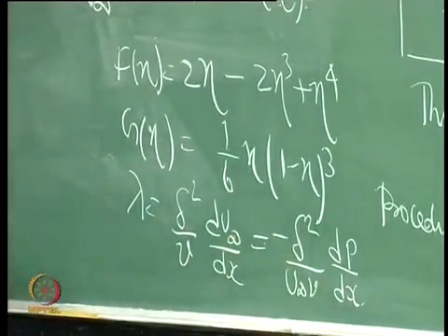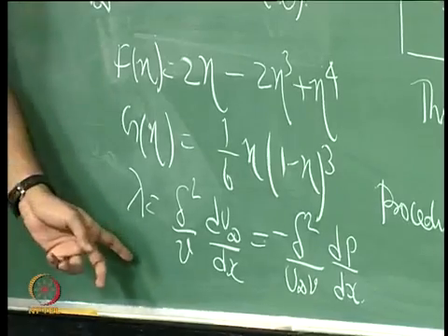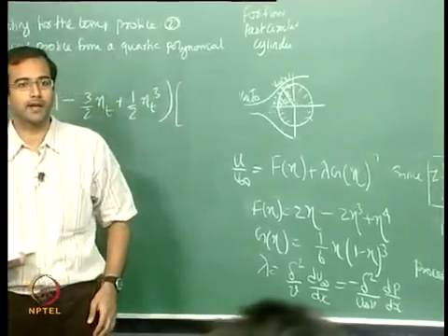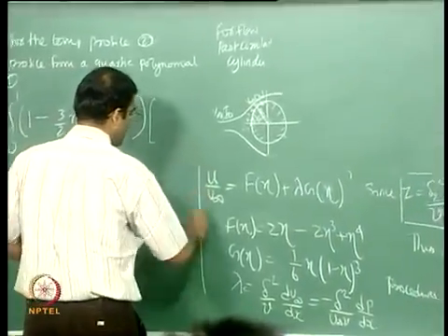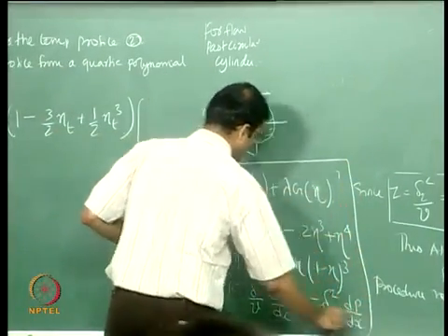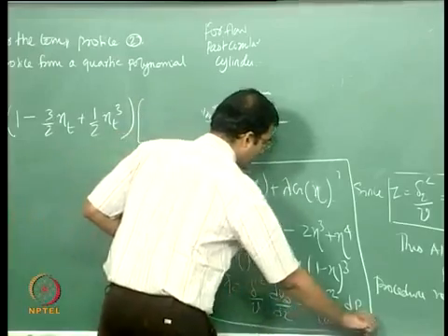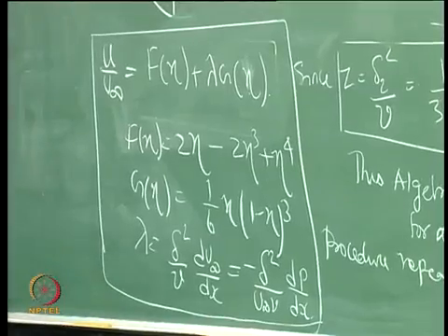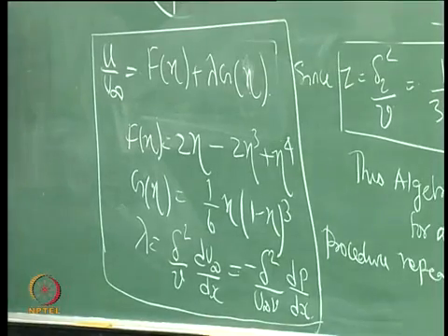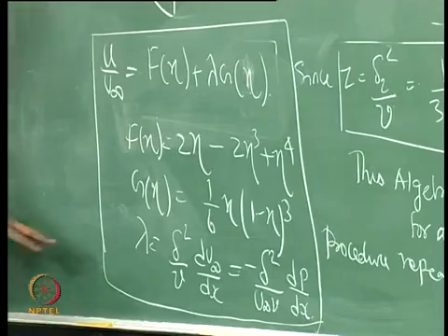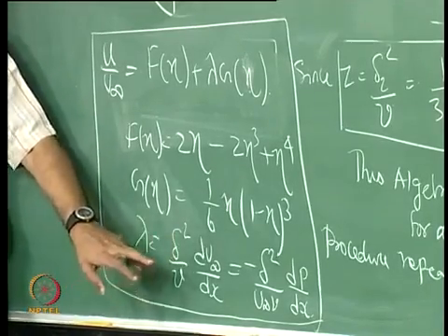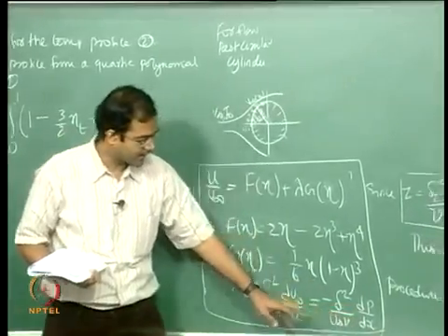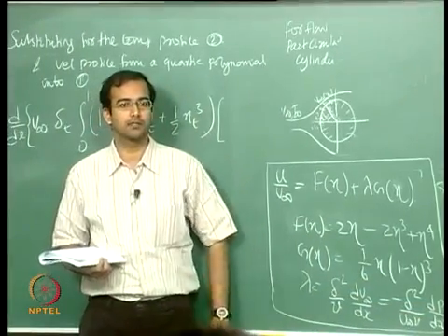So for flows with adverse pressure gradient, your lambda will be negative. With favorable pressure gradient, lambda will be positive. So this was the velocity profile that we derived yesterday, assuming a quartic polynomial and satisfying those 5 boundary conditions. Okay, so your lambda here is the non-dimensional parameter, which is giving us something like a ratio of your pressure forces to the viscous forces.